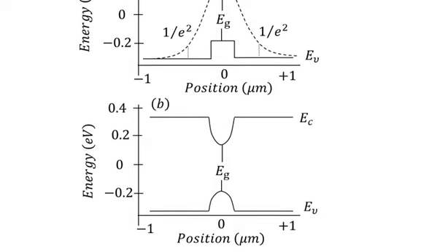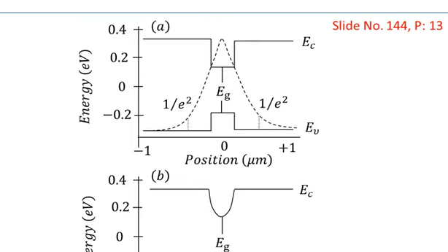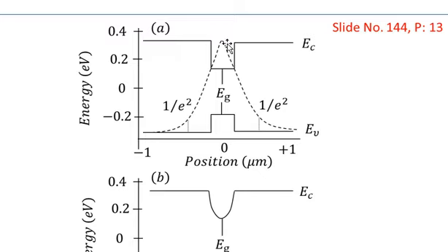So the optical mode intensity profile has been shown for part number A. You can see that this is the intensity, and this intensity is gradually decreasing. It is maximum in the center of this gradient index region. In the center, the beam intensity is maximum, and away from that, I have also shown the 1 over e square points, where the intensity drops to 1 over e square on both sides of that. Those points have also been shown.